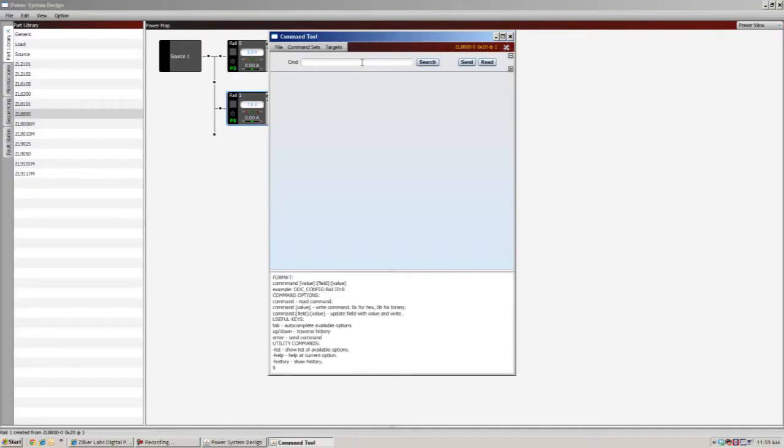So let's start with something simple like the output voltage command. I'm going to go back into this command line tool and start typing the VOUT command. The PMBus command is just VOUT_COMMAND. So double click on this and it pops up and says I have it set to 1.5 volts, which is a hex command of 3000.